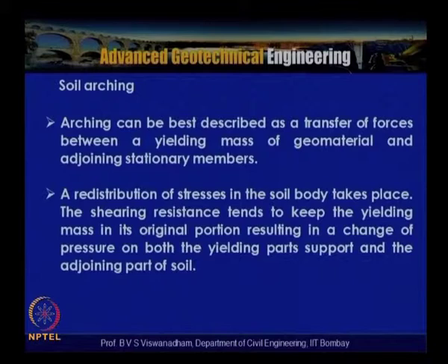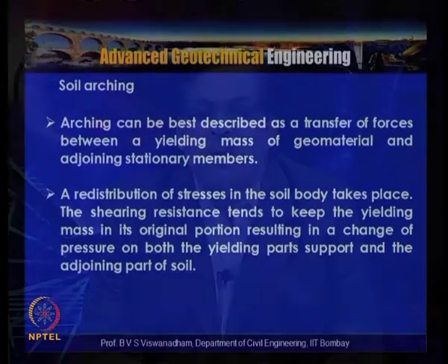We have also discussed this topic of soil arching when discussing slope stabilization using piles. We said that when piles are placed very close to each other, with a center to center distance, at an optimum location within the slope, the participation of arching is visible.